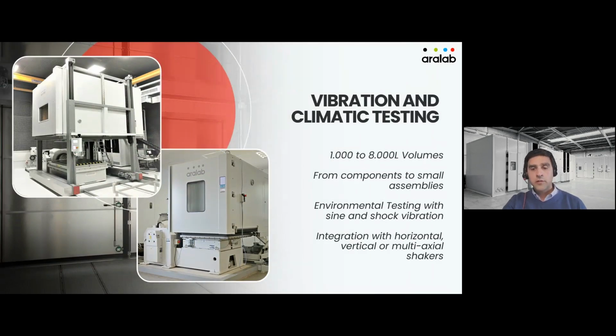So, vibration and climatics testing. Again, we are joining climatics, temperature and humidity, cycles of temperature and humidity, with vibration. And then vibration can be a simpler sine vibration, or it can also have shock vibration. In this case, we work closely with our users, and with the shaker suppliers as well, to determine how the chamber and the shaker interact.